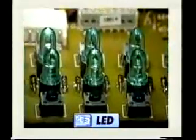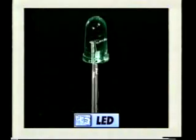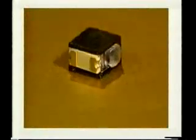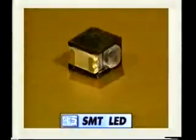One type of through-hole diode, which is usually radial leaded, is the light-emitting diode, or LED. LEDs radiate light and also have an anode and cathode side. The cathode, or negative side, can be identified by a flat edge, notch or tab, a dot or shorter lead. Surface mount LEDs are less common and usually have metal terminations.